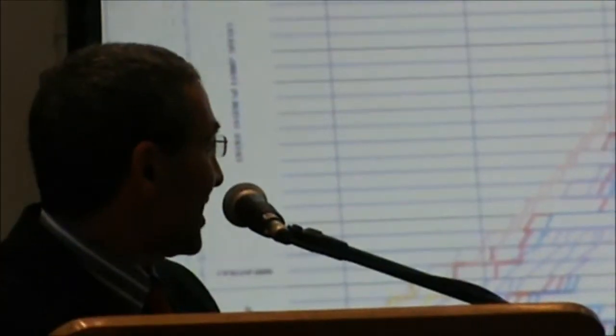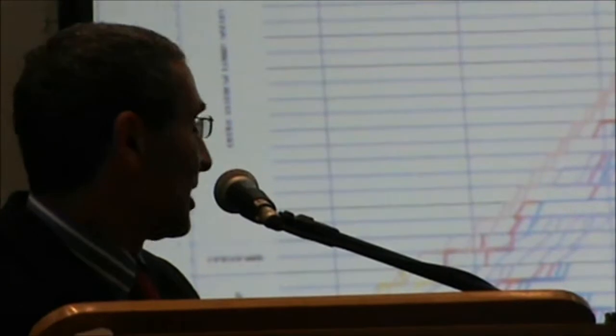But if we adopt the width reduction strategy, and if we model it using a discrete event simulation, then you start to get results like this. And you see that the difference is that here, the work in any particular floor, like here or here, is bunched together so that we get shorter cycle times, more intense work to finish a product, get out of that product, remove it from the work in progress, and generally the results are much better. You can see that still the sequence is not necessarily one floor after the other, and that's because we use a strategy called process pull that I'll explain a little bit more about in a moment. So these are the good results.